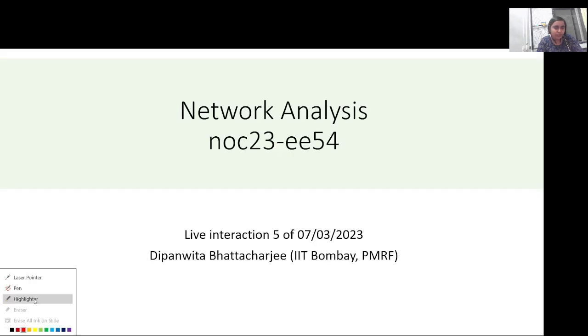So today for the tutorial, we'll be doing a few of the problems, like solving a few of the circuits by using Laplace transform. Before we go into the solving of circuits, I hope everyone has gone through the videos where Sir showed that any signal in the form of x of t can be converted to the frequency domain using a Laplace transform, which is equal to the integral from minus infinity to infinity of e to the power minus st, the signal whichever it is, into dt. This is the basic way in which it is converted to the frequency domain.